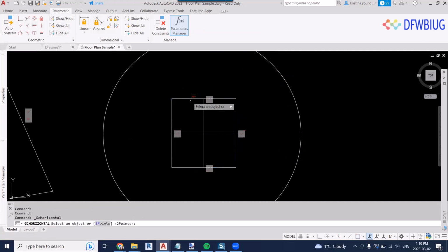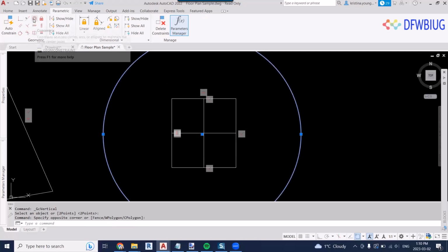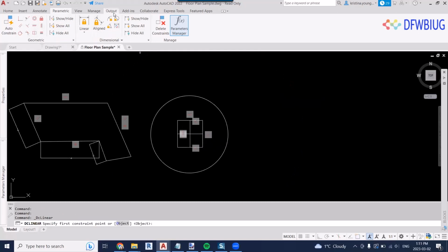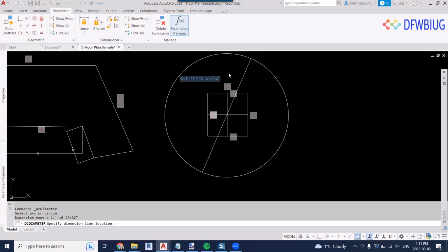I'm not saying, Tom, that this is what you're going to utilize it for, but in case, whatever your object is, probably going to mainly be blocks. But we're going to go to this circle and we're going to define its point. Ooh, I don't remember if it lets me. Okay, so we're just going to go dimensions. There are other ways to do this, I'm just trying to do it quick. And again, I don't use your application right out of the gate. So we're going to set a diameter here. We'll give it 10 feet.